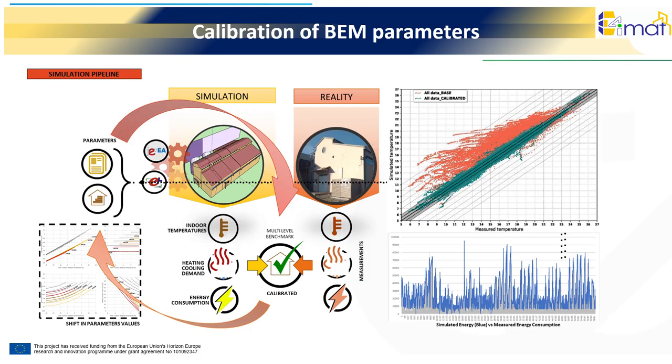It is important that the base BEM undergoes an initial result assessment where its functionality and performance are studied prior to the parametrization process. The results from this initial run are indispensable for establishing how the model reacts and selecting the key parameters that will be calibrated. The selected parameters are then optimized based on an objective function. An objective function is a mathematical expression that aims to reduce the gap between simulated results and reality. It can usually be expressed in terms of minimizing residuals or using statistical indexes suggested by international standards.